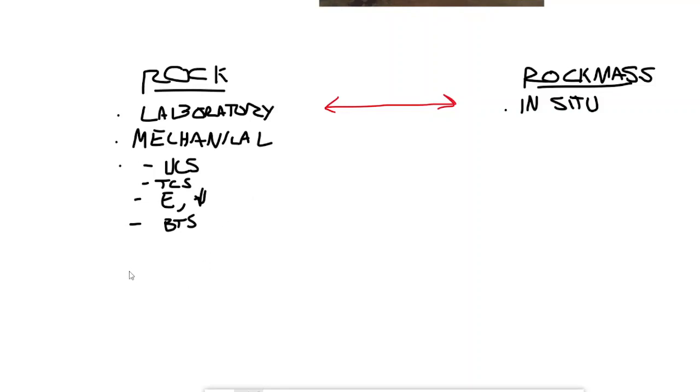And then what we can do with that is make a very scientific measurement, right? If we're looking at UCS specifically, then maybe we would cut the core to an appropriate size, grind it down, dry it, and then put it in a test cell, a hydraulic press, and make sure we can record the stress as well as using extensometers or strain gauges to measure the strain. And then we'd have our stress-strain curve. We would find where it breaks, call that sigma yield or sigma fracture, and record that as our UCS.